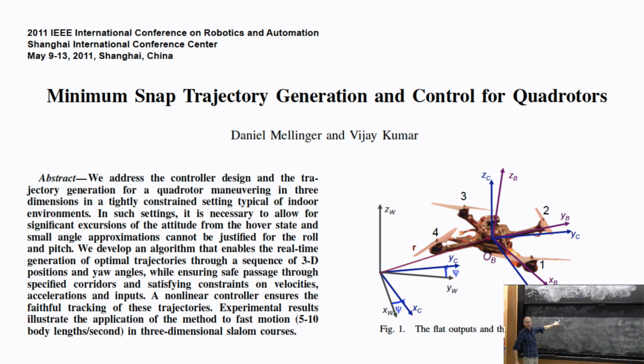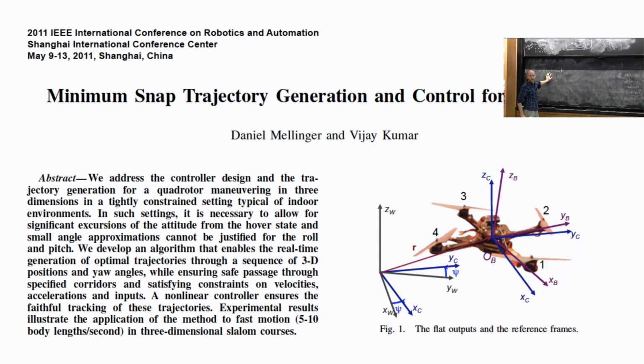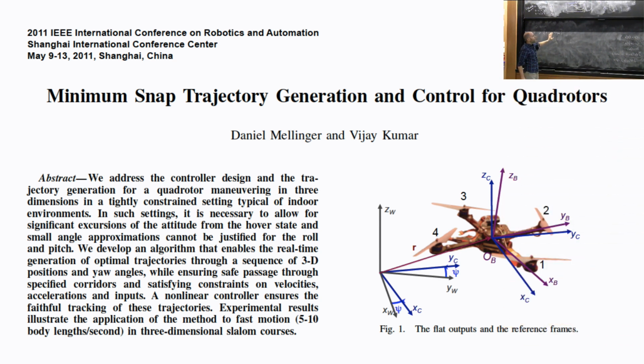The reason you need, so first of all, the 3D quadrotor model, when you write it down, if you only do the free body diagram the way I did for this, then you get a system that you cannot stabilize at the top even. The fixed point is not stabilizable, and it's also not differentially flat.